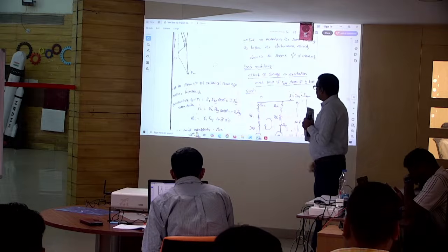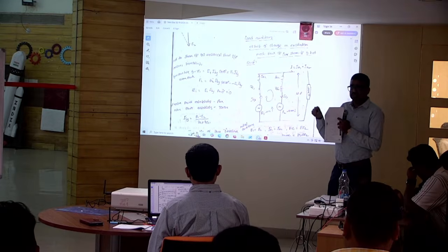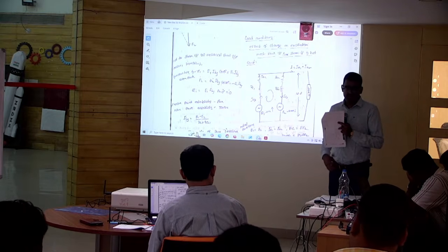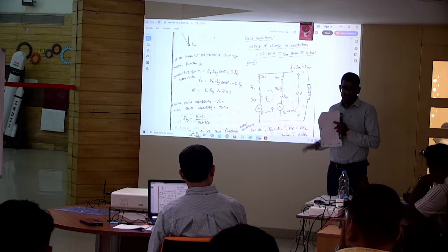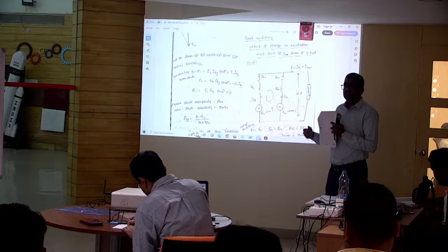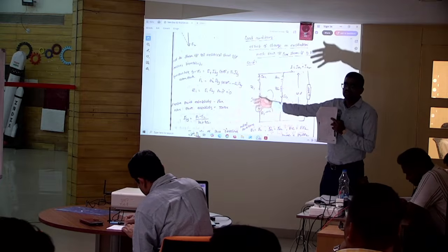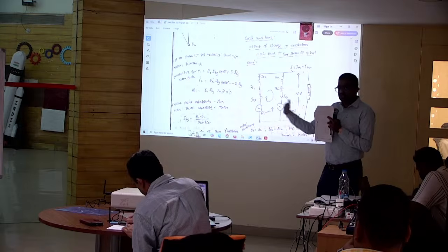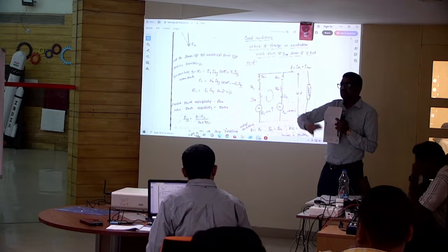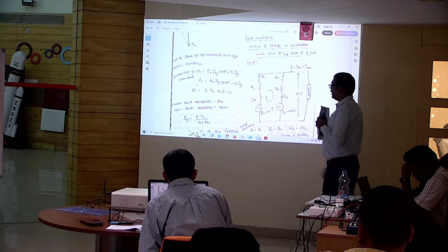As I discussed, these are the points to consider. Reactive power always tries to establish the flux. This is also called the magnetizing component, or magnetizing power. Induction machines are always under excited. In the case of induction machines and transformers, we need magnetizing power to establish the flux. Only then will the other operations be affected. After the magnetizing power, we transfer the entire input power, the active, utilizable power input. So reactive power plays a major role in parallel operation. And the magnitude is now similar.